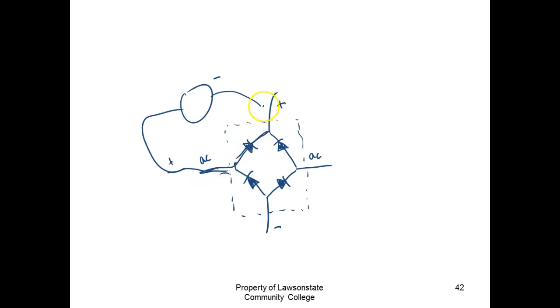Then what I would do is I'd leave, so notice we got the minus on the what? The plus. Then I would take my plus lead on my meter and I move it right there. Now I'm doing what? I'm checking the other diode, right? You understand? I'm checking this right here, right? Then what would I do? I'd put my minus on the AC, then I'd put my plus, and then I would touch it to both sides. Right? You understand that? Yes or no?